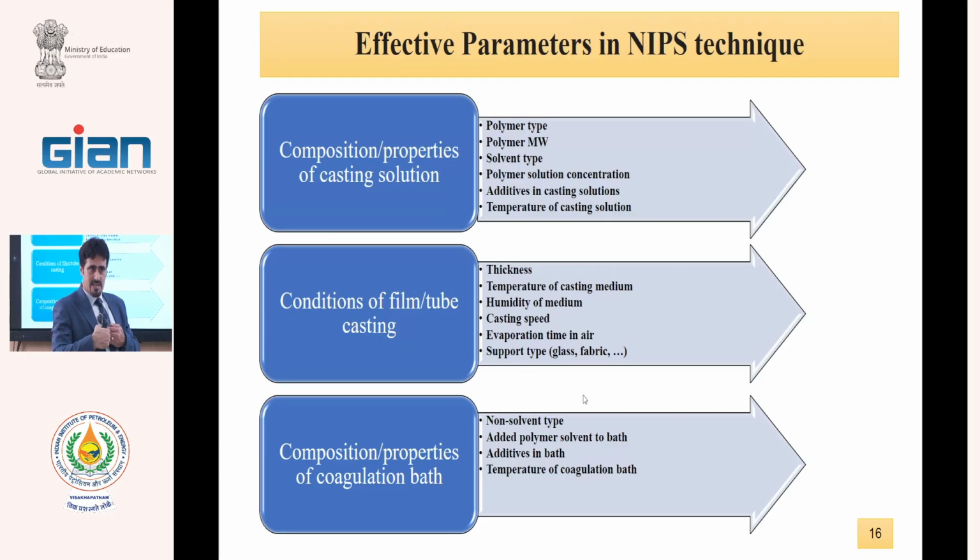When we cast and go to the coagulation bath, we have 3, 4, 5, 6 seconds between casting and immersing in non-solvent. One student is rapid, in 3 seconds, another student is slow, with 10 seconds between the casting and immersion. Therefore, this contact with air is very important, and this is the main reason for change in flux from student to student.